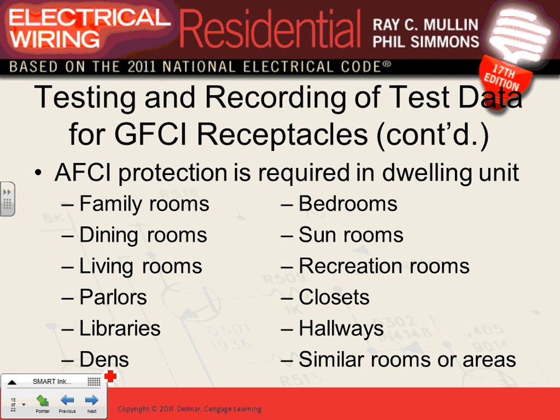So in our project, you're going to list all the circuits that feed all these areas, receptacles and lights, as arc fault circuit interrupters. And what's the difference? $7 for a circuit breaker versus almost $35 to $40, the difference between an arc fault circuit interrupter circuit breaker and a regular 15 or 20 amp circuit breaker. Okay, so in every family room, I can't emphasize this enough, this is for lights as well as receptacles. Lights and receptacles in all these areas.